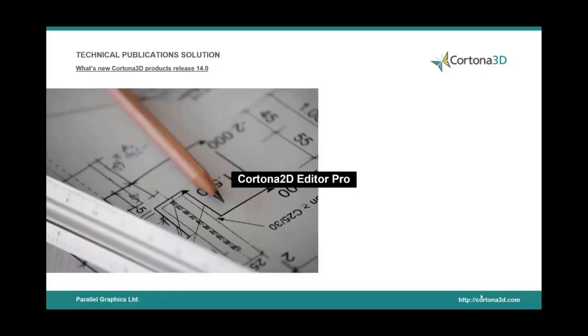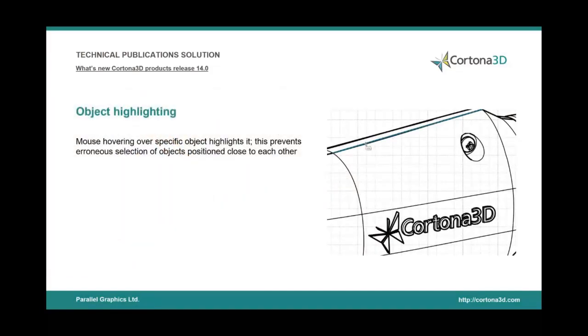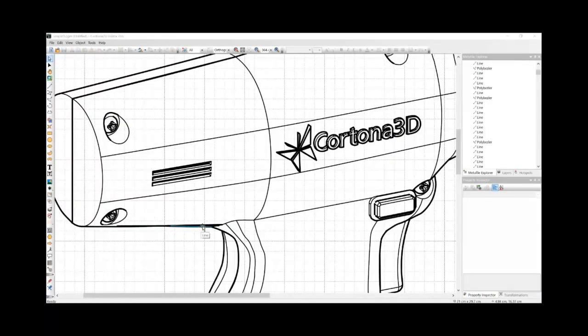Let's move on to our second subject, which is Cortona3D Editor Pro. And the first feature is the object highlighting. As you hover with your mouse over an object, it is being highlighted, as simple as that. This is particularly useful whenever you have multiple objects lying close to each other, overlapping each other possibly, and you are simply unaware which object you are about to select. So this prevents you from erroneously selecting the objects that you don't really want to select.